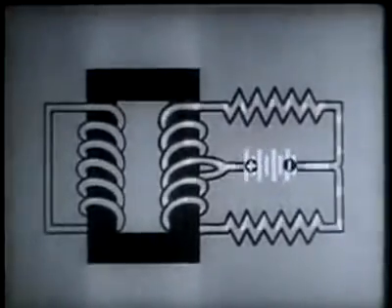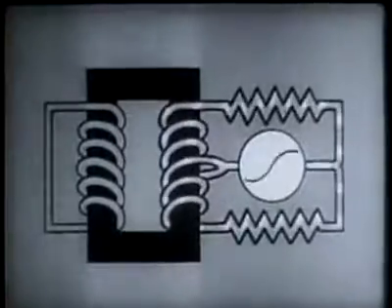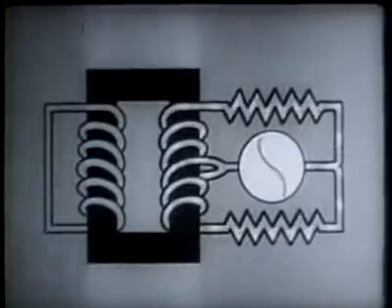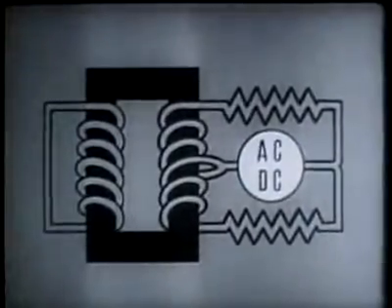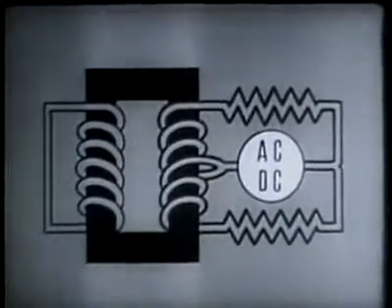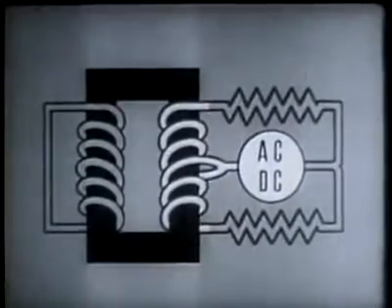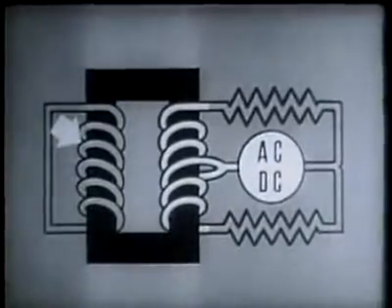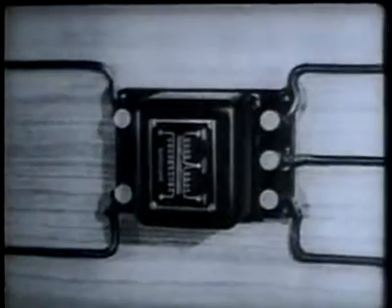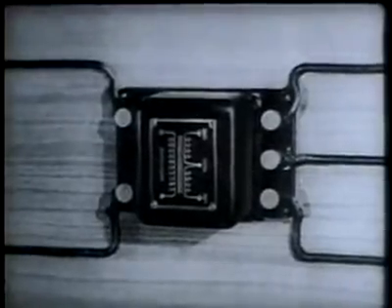The same principle applies to alternating current. This is the third and most important operating principle of the repeating coil. When either alternating or direct current is introduced at the midpoint of one winding and is made to divide equally between the 2 halves, no effect is produced in the other winding. This principle is most important, for it permits 2 channels of communication over a single circuit.